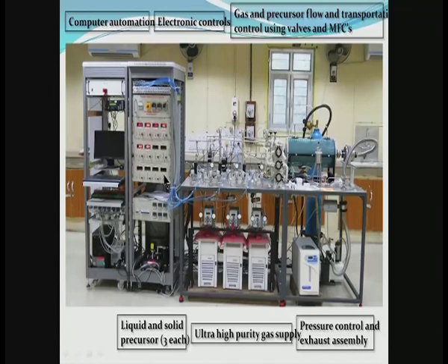What is shown here is the photograph of a system that can do both ALD and CVD. So, this is the deposition chamber, and all of this is valving, as I said, high speed valve mechanisms for switching rapidly between precursors, and these are chambers in which precursors are kept at constant temperature, so that the dosage in each pulse is exactly the same.